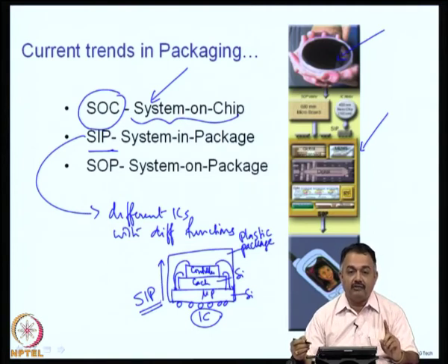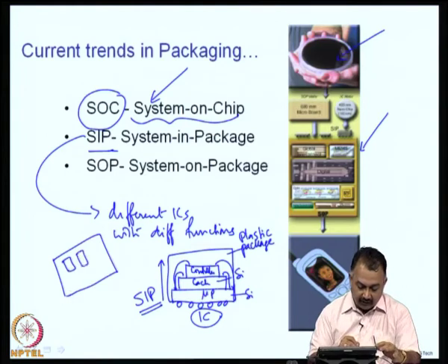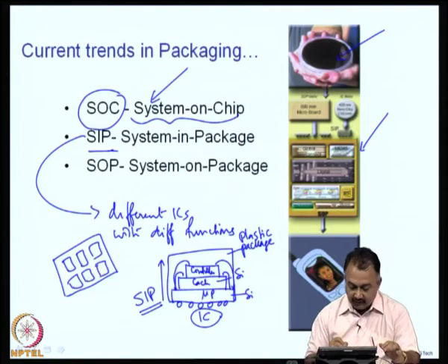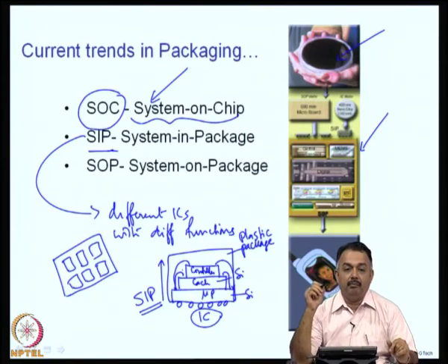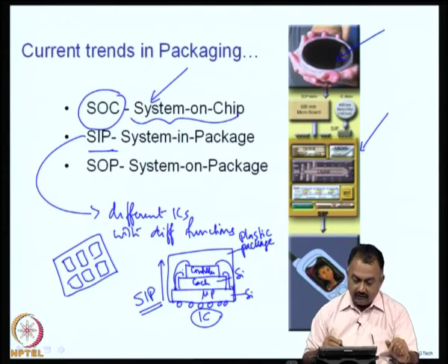This is different from the multi-chip module concept that we have seen. In a multi-chip module, by textbook definition, the dies are placed on the same substrate, in the same plane, but here it is more or less built one on top of the other. So, this reduces space, and it utilizes the entire area under the bottom die for providing your IOs.